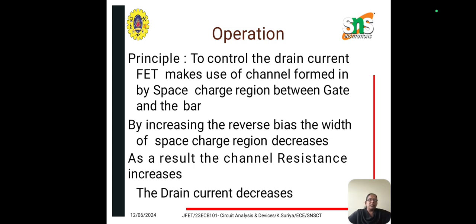When the PN junction is reverse biased, little current flows into the gate junction. When the gate voltage is made more negative, channel width decreases until no more current flows through it, and the FET is said to be in the pinched off region. The voltage at which the channel almost closes is called the pinch-off voltage.